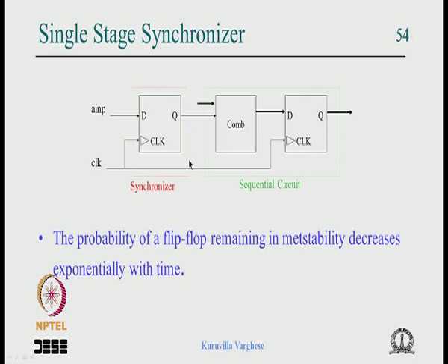It is probabilistic. We cannot say deterministically that 100% of the time it will come out, but we increase the probability, okay. So metastability we can only handle probabilistically. What we do is increase the probability to such an extent that in the lifetime of the system we are building, this happens very rarely. That is the basic idea behind it, okay.